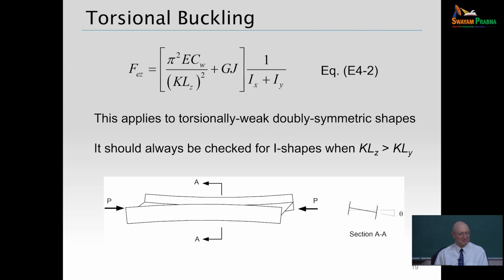So the confusion arises because of this. Here the J term is something different, and in circular sections we call that J term the polar moment of inertia. Right. J is not the polar moment of inertia here. It's the St. Venant torsion or uniform torsion constant. We start the derivation from circular and then we deviate here, so it becomes a confusion. Right. Yeah. For a circular section, J is, let's see. Okay. Yeah. There it is. The polar moment of inertia.